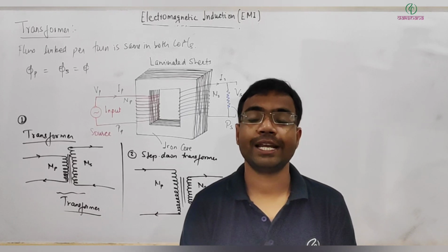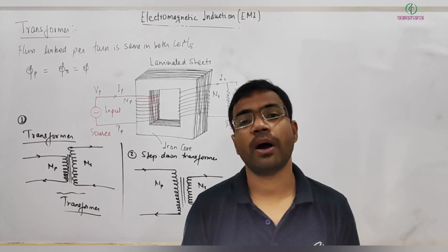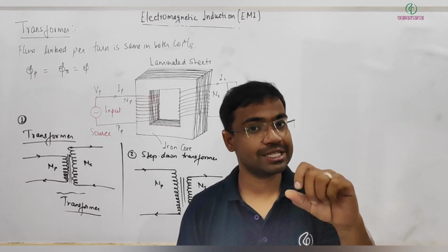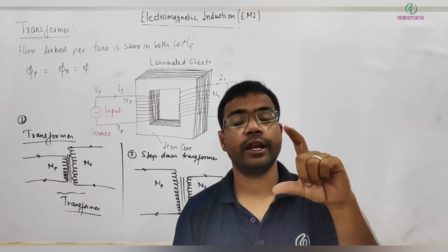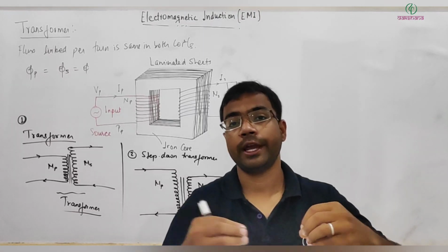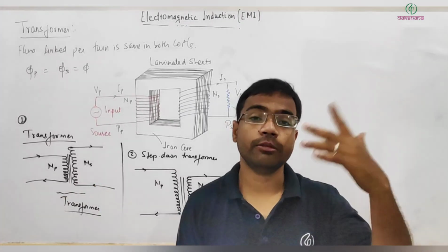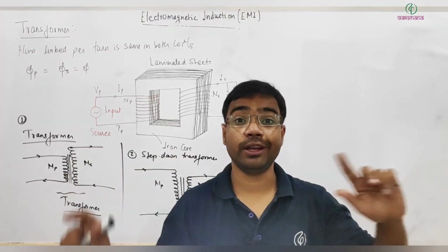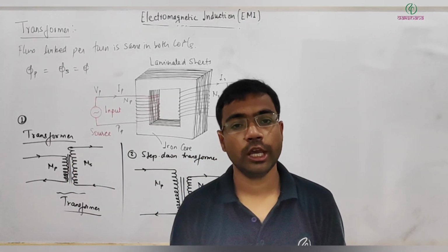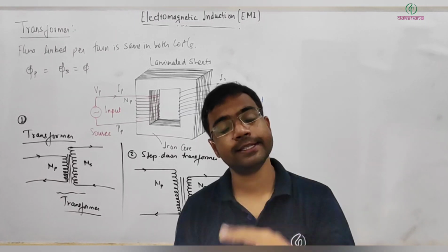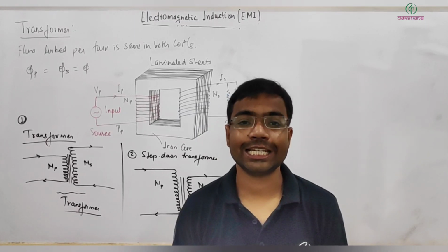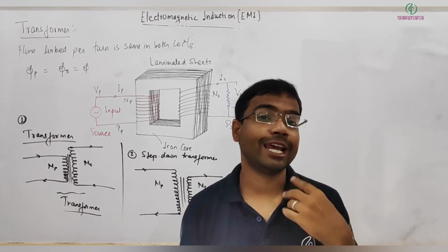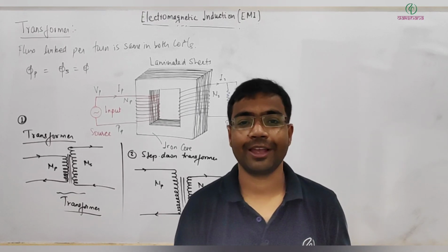So the point is that if we are transferring the power at low voltage, that means the current will be higher. You can see the power lines; power comes from many, even thousands of kilometers, so the resistance of this power line will be very high. Getting it? With high current and high resistance, the power loss in transmission will be I square R, very high. It can even sometimes melt the wire cable.